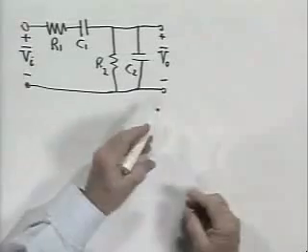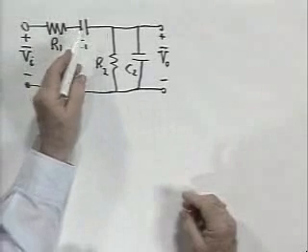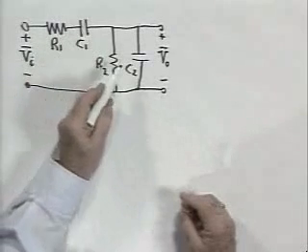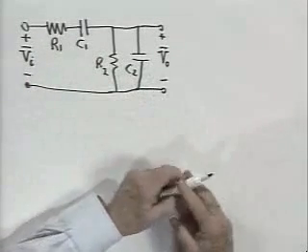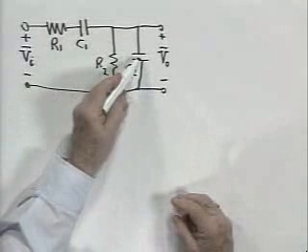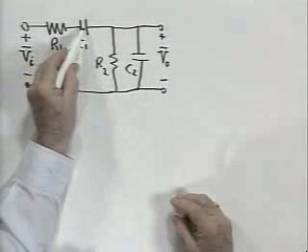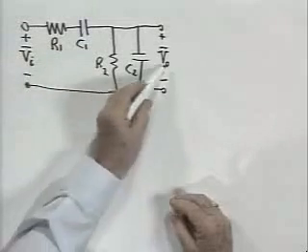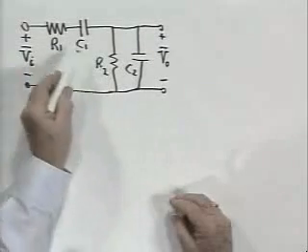This is a circuit which you've seen before in homework. It has the capacity of functioning as a bandpass filter. If we choose these elements properly, in particular, if this capacitor C1 is bigger than C2, more precisely if the time constant R1C1 is much, much larger than the time constant R2C2, there's a range of frequencies in which this capacitor looks like an open circuit and this capacitor looks like a short circuit. In that case, this is simply a voltage divider, and the voltage transfer ratio, V sub O over V sub I, is R2 over R1 plus R2.